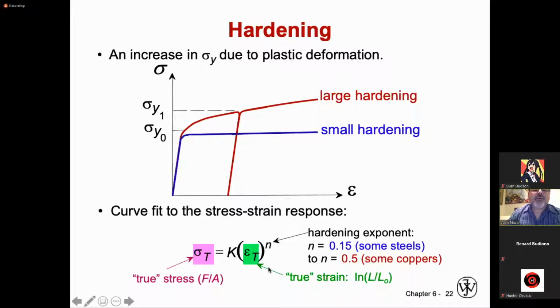I will give you an exercise that we're going to work together in order to calculate the hardening exponent from that knowledge of transformation. This particular question is usually 10 points, and it is associated to that question that you were analyzing last time in class when we were looking at a stress strain engineering diagram and dissecting from that diagram all those 7 mechanical properties. After you know how to translate from engineering to true strain, there is an additional calculation you need to make, which is defining the straining or hardening exponent. This will allow you to make a judicious choice whether it is worth spending the effort in hardening a non-ferrous alloy by plastic deformation.